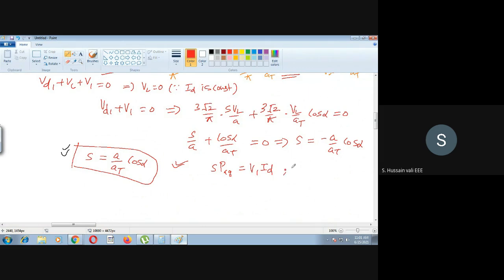But before we simplify, we recall the equation between the torque and the air gap power. This also comes from the previous induction motor classes. Air gap power is T into omega S. The relationship between torque and gross mechanical power is that gross mechanical power is equal to T into omega R, whereas air gap power is equal to torque into omega S, not omega R. So this we already studied. You recall that.